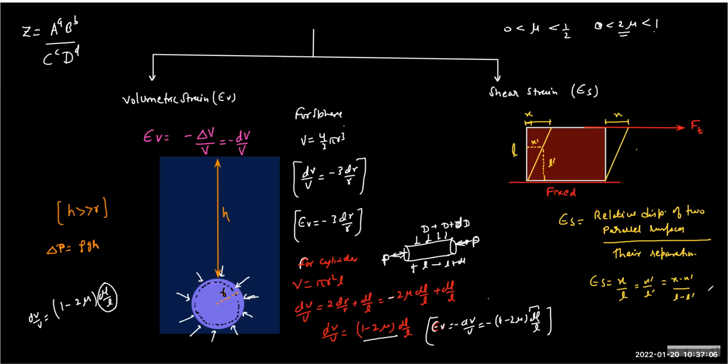Now, in this way we can define it in 1,000 ways, so the best way to define it is by taking this angle as theta. When you take the angle theta, and these displacements are really small, as I said in the very beginning, we can think of theta as tan theta. For a small angle, we just write tan theta as theta. And this gives the definition of shear strain: shear strain is defined by only a single variable, theta. Understood?